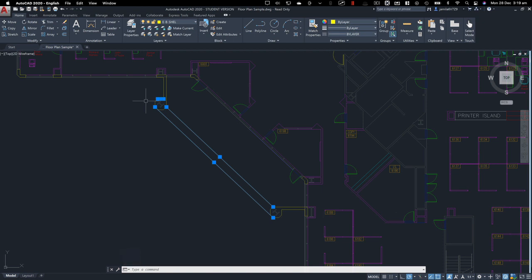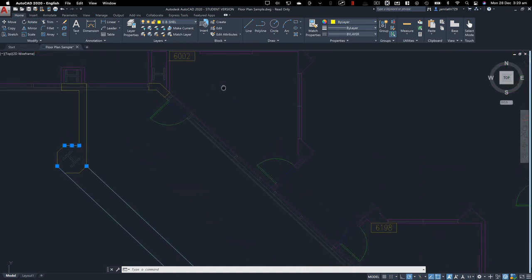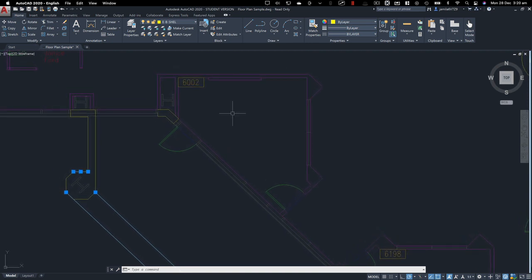But let's say you want to select multiple objects at once. So how do you select? Let me zoom into this part and I'm going to pan by using the mouse wheel. I'm going to click and then release the mouse button. I'm clicking the left mouse button. And now while I'm in this mode, I'm going to move my mouse and you'll see this greenish area, which means this is a selection area. Any object that touches this will be selected.